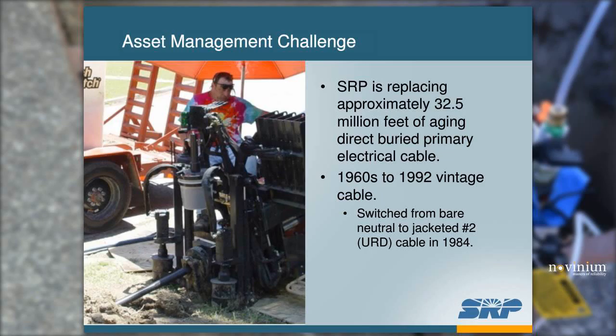So the challenge before SRP with underground cable is we have, at this time, roughly about 32.5 million feet of direct buried cable in the ground. It's primarily cable that was installed from the late 60s up through 1992. One other date of note for us is all of our cable is jacketed except for number 2 cable prior to 1984.